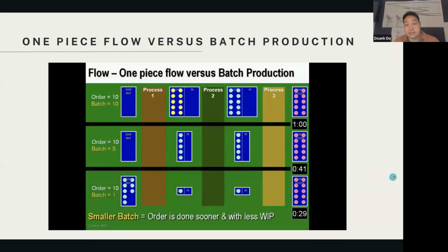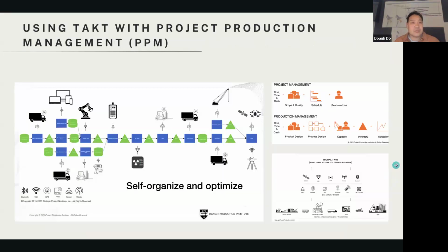So yeah, TAKT is really mathematical, right? Because once you know the zones, the rates, the trades, you can simply calculate how long it'll take you to finish the project, which is good because as long as you don't mess up and as long as you can follow your steady plan, you have a very reliable way of finishing the project on time. But also in between, as you change the parameters like the trades, the zones, how many people you have working per trade, you can also influence the work itself, right?